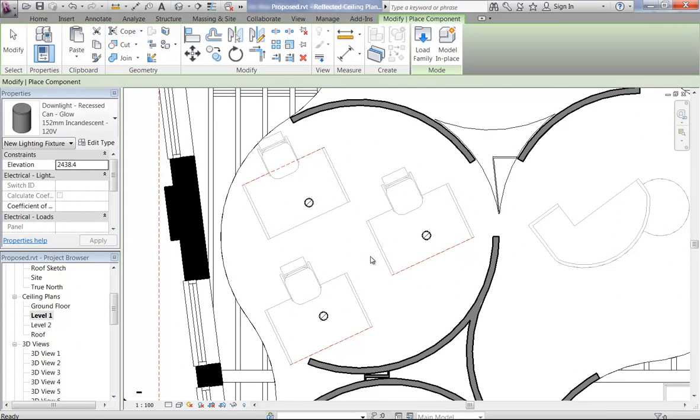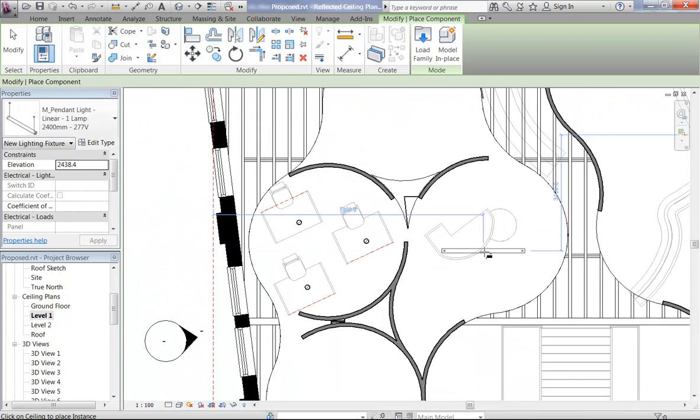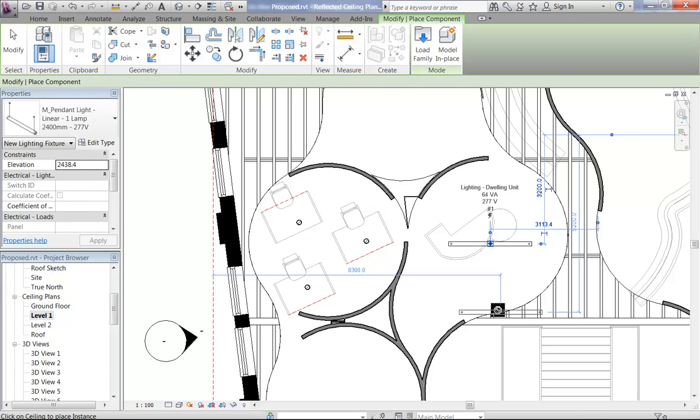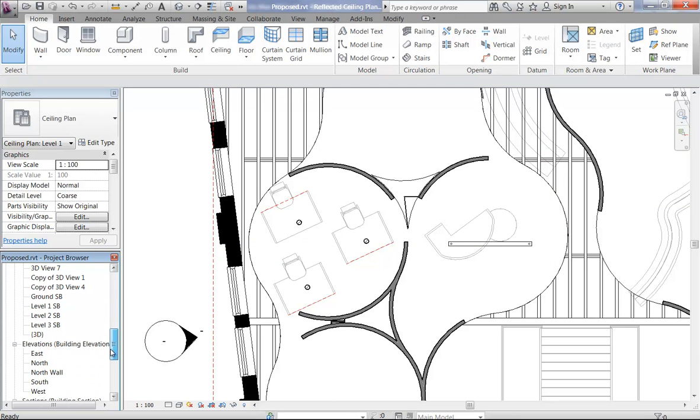So when you model the ceiling, like model in place, you have to choose a ceiling that you can model in place, right? So the Revit will understand that this is a ceiling cover. Exactly. It's just a category, but then it'll let the lights be hosted by that. So yeah, that's why I'm going to change this one.